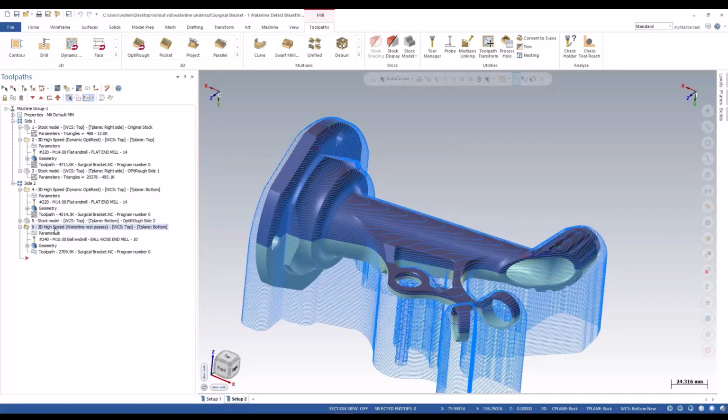So this is the Waterline toolpath that I've created so far, and there's two things that I don't like about it. The first one, if you look along those shallow faces along the top, see how wide that step over is? It's a consistent step down, but it's a really wide step over, which really isn't helping our surface finish. And then there's a bunch of wasted motion at the bottom. After it's finished cutting all the stock, it just keeps going to the original stock depth.